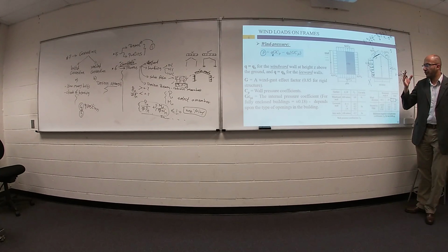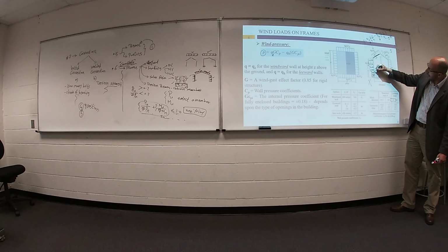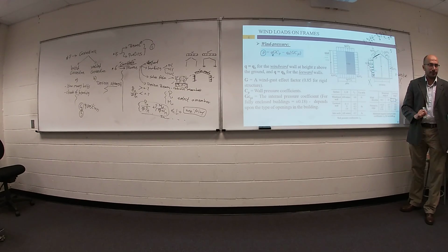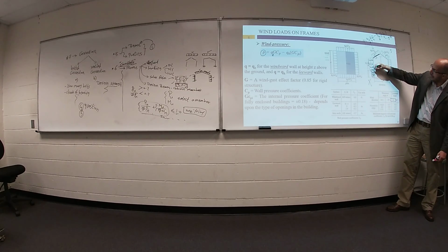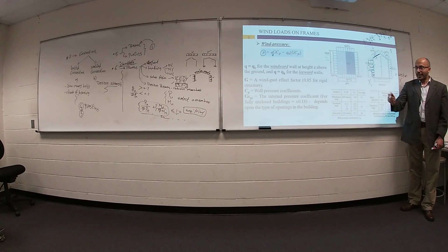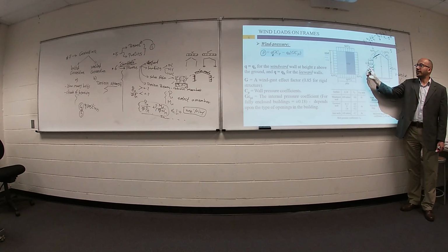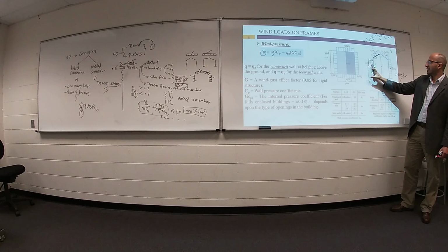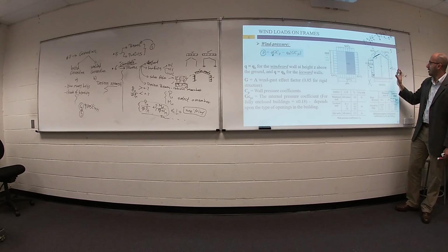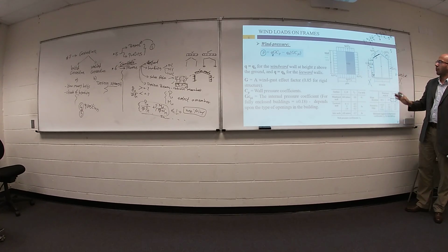Also, if you want, for this one, I can use also Y, because your vertical member has local axis X and local axis Y. So I can enter this value in negative small y, but I don't need to use this local axis for any inclined, vertical or horizontal member.